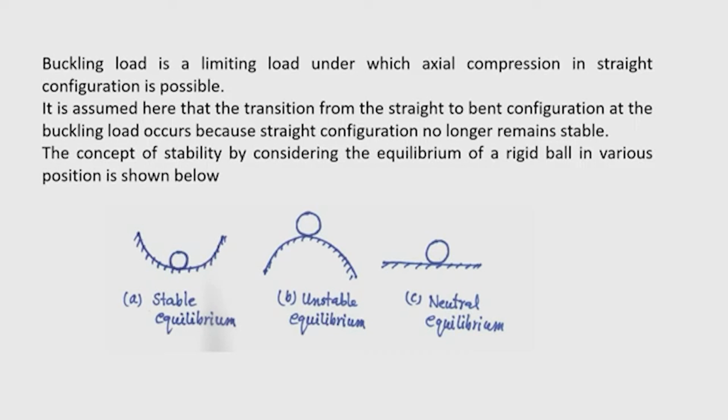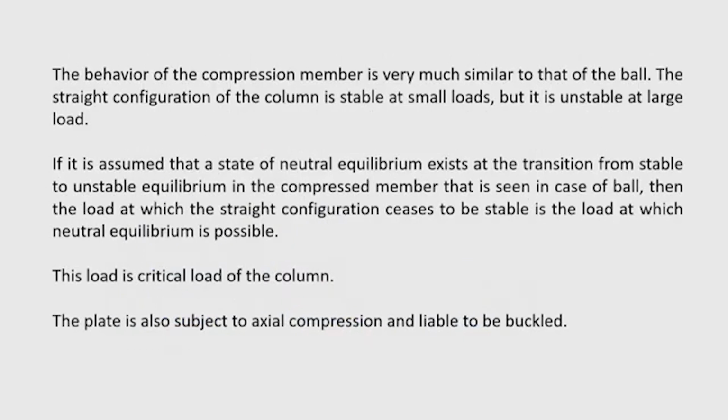Okay. Now, we shall try to find out the buckling load of the plate, but before that I want to find out the differential equations of equilibrium considering the in-plane forces, because buckling is only possible when there is an application of axial forces, and these axial forces must be compressive. So, we shall today derive a general expression for the differential equation of the plate considering the in-plane forces in addition to the transverse load.